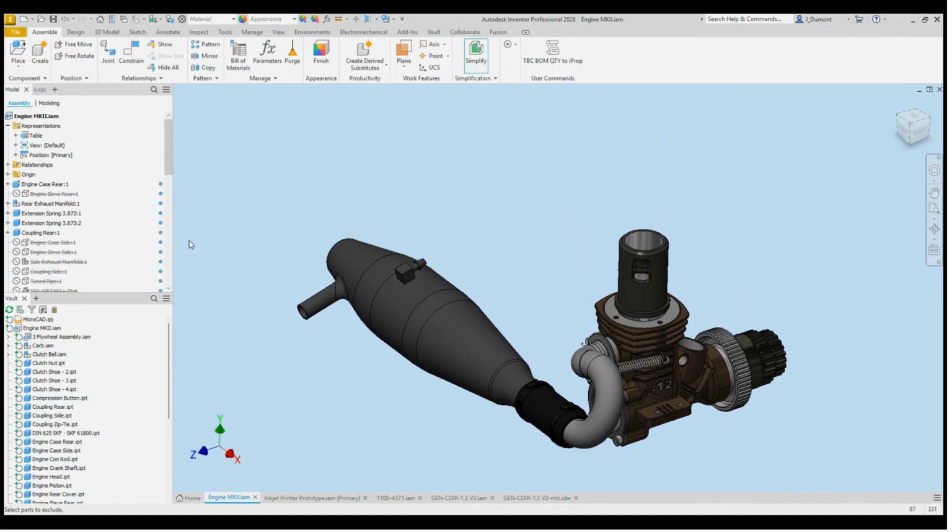And in here, here's the holes. It's going to remove all of them, or I can say none, and I can select which ones I want, or a particular range. But in this case, I'm going to remove all of the holes and all of the tunnels. The tunnel is basically a feature that goes all the way through the model. It's a void. So it can be a square, it can be a circle, not necessarily a hole, but it's a volume that you want to remove.